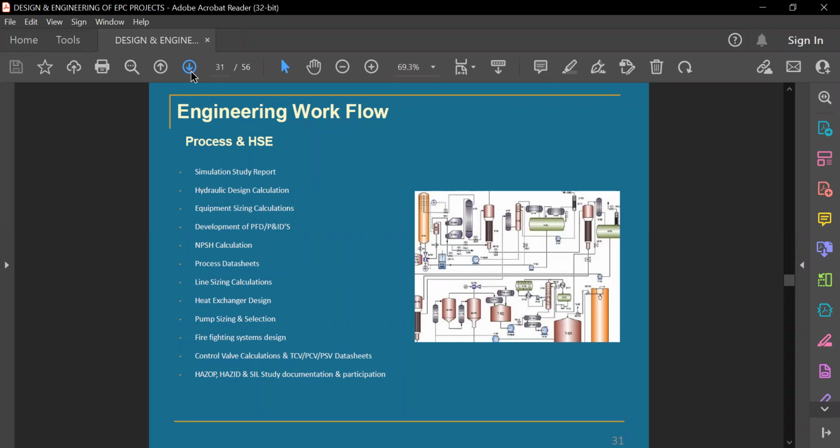And if it recommends any other instrumentation or any other valve to be added, generally not deleted, but generally they will ask to add a safety valve. For example, if the tank is having any pressure inside, then the tank should not get blasted. He will ask, then we will say that okay, a level transmitter and a pressure transmitter are there, and if the pressure transmitter fails, or the level transmitter fails, then we will say that okay, we have a safety valve, we have the emergency relief valve, we have the other devices which are mechanical, which will definitely work.